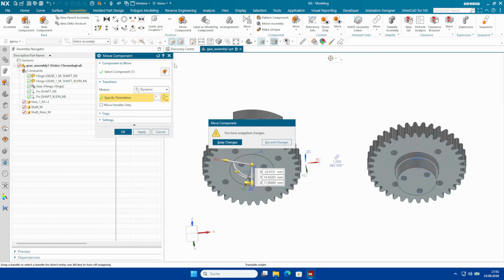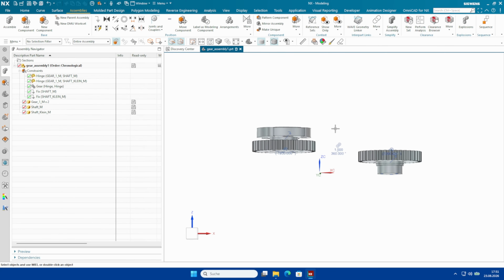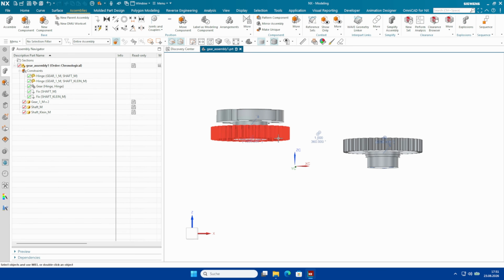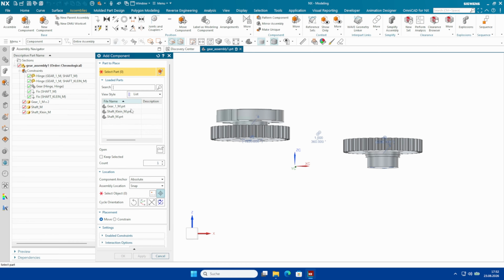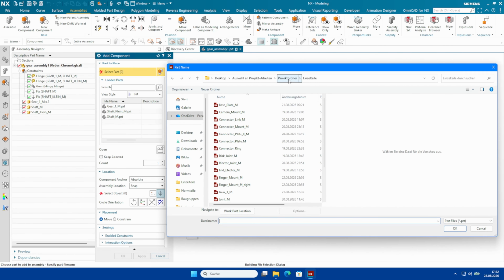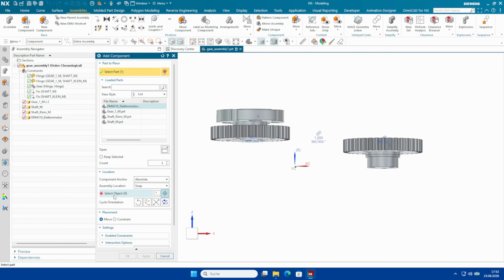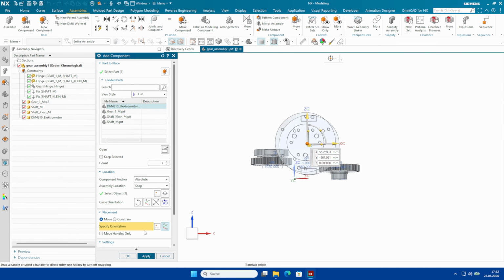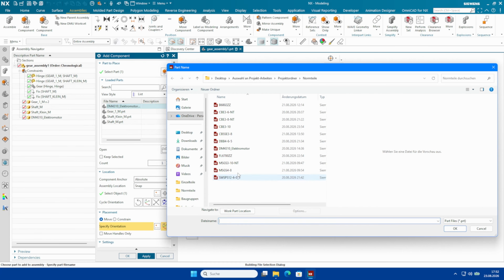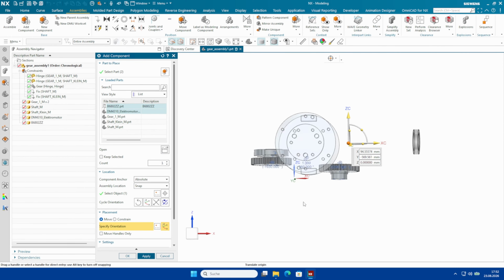So to solve this problem, I would need to have certain amount of other geometries which I can assign as fixed at their particular axes. To explain it in simple words, I will add two more parts to each of the axes and constrain them to the gears. So let's add those components. One of them is my motor, which is going to power my first gear. And the second one is going to be a ball bearing, which is going to constrain my second gear.